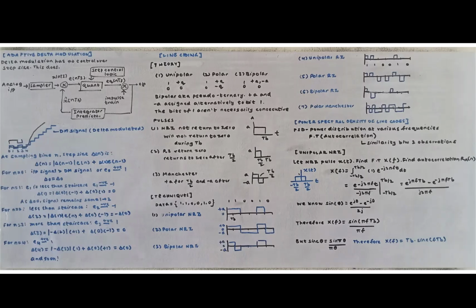This is probably annoying to remember, but the additional motivation for you to remember this is that this same Fourier transform of the input signal, as the first step, is going to show up for every single return-to-zero derivation ever. So in any derivation, this is just probably free 2 to 3 marks for you. Just take the input signal, calculate, or pretend to calculate at least, the Fourier transform, draw that small mini waveform, and write T_b sinc(fT_b).